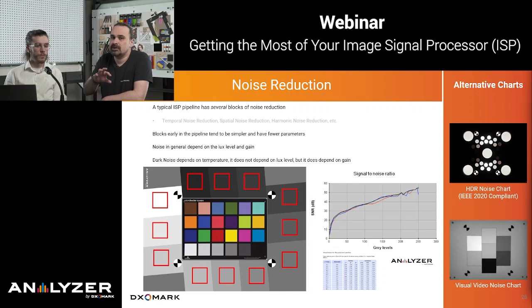Instead of looking at how much noise you have, because then it depends on whether I'm looking on a dark patch or a bright patch, engineers that do image quality often discuss in terms of signal to noise ratio. So this is the curve that I'm plotting on this page. And this particularly is done in a logarithmic scale called decibel or dBs, because that correlates more strongly with human perception.